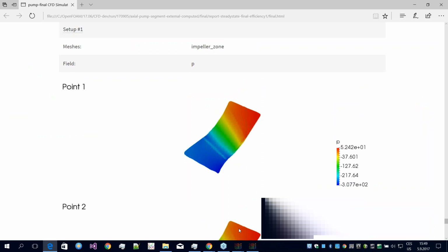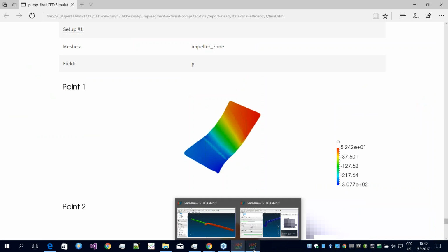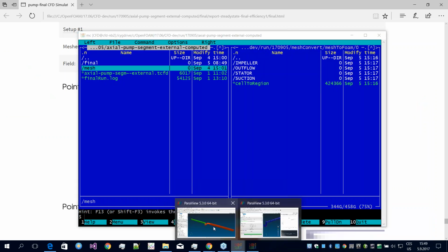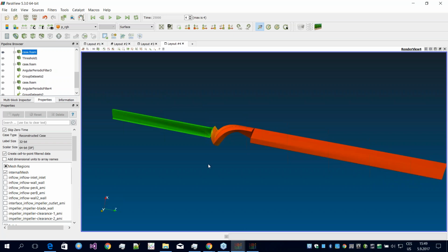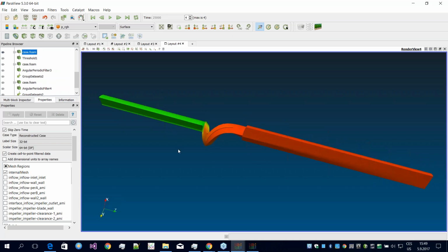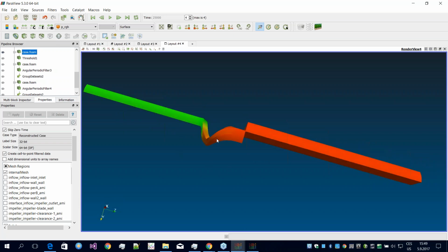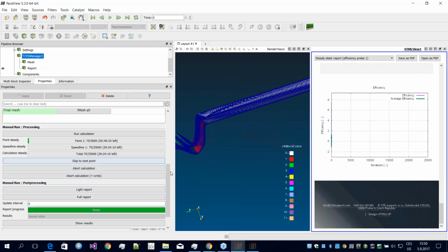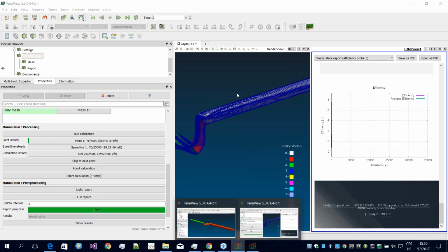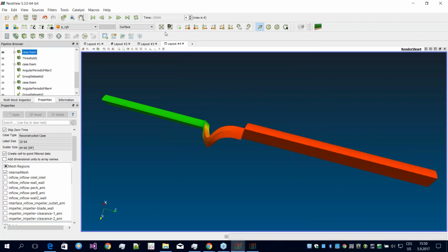And give me please just 1 minute to show you some evaluation which you can do directly in ParaView or your visualization. So basically, you can load the case anytime using this button, which is here. So here you can click on show results, and the results are automatically shown and appear in the render view, and you can work with them.